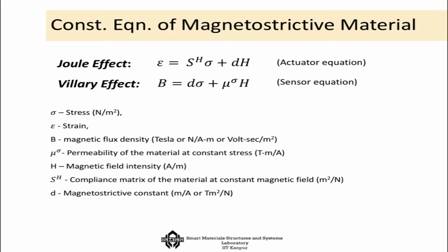Now, the constitutive equations of such materials are very similar to those of piezoelectric material. From the actuator point of view, we will generally use the Joule effect, and in the Joule effect, if you apply the magnetic field H, you will see the strain, which is the deformation. We can use that deformation either by restricting it so that you get a force, or by change of length of the system. Remember, if there is a change of stress, deformation also occurs, but that's not smart material behavior, because that happens for any system.